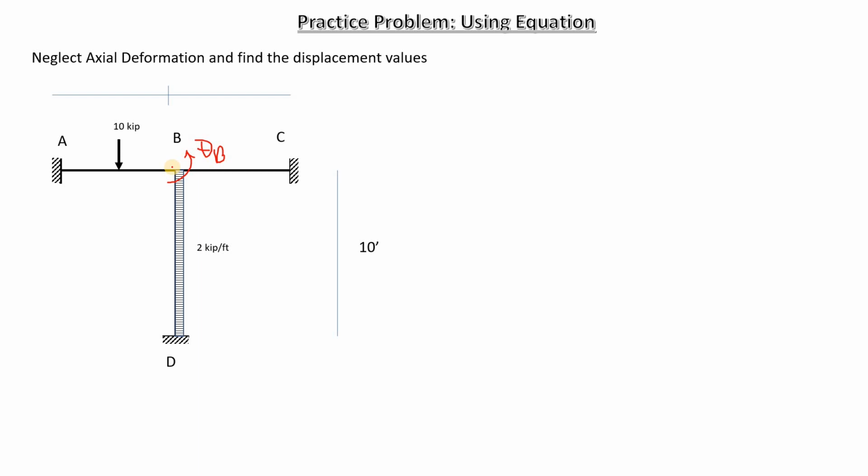So every adjoining point that is with B point will be given a fixed support. In this case, they're already having a fixed support, but if they didn't have a fixed support, they would have done that. So I'm drawing the new diagram here. There you go, the diagram for the deflection. And here the unknown is theta B. So let's write up theta B here.